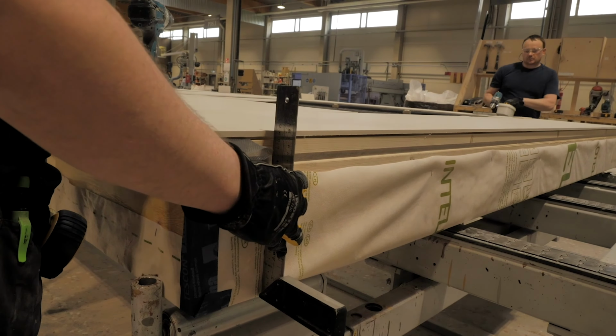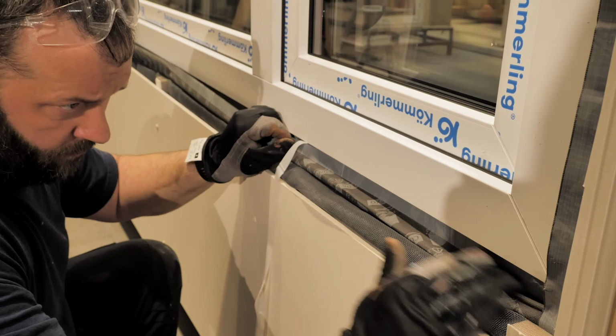Before proceeding, conduct a quality check to ensure that the window units and glass surfaces are undamaged. When installing the window in the facade element for renovation, follow the specific guidelines provided by the window manufacturer, just as you would for a typical external wall element. Pay special attention to taping the windows to prevent any water and air leaks.